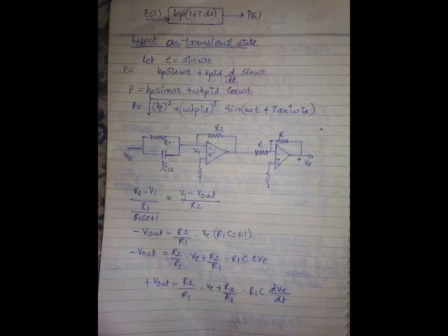This controller is capable of eliminating error, and the response of this controller to errors is slow. So when you use this controller with any plant, the overall response of the system also will become slow. The speed of response of any control system is always defined in terms of rise time, not settling time. So what is the effect of this controller on rise time?